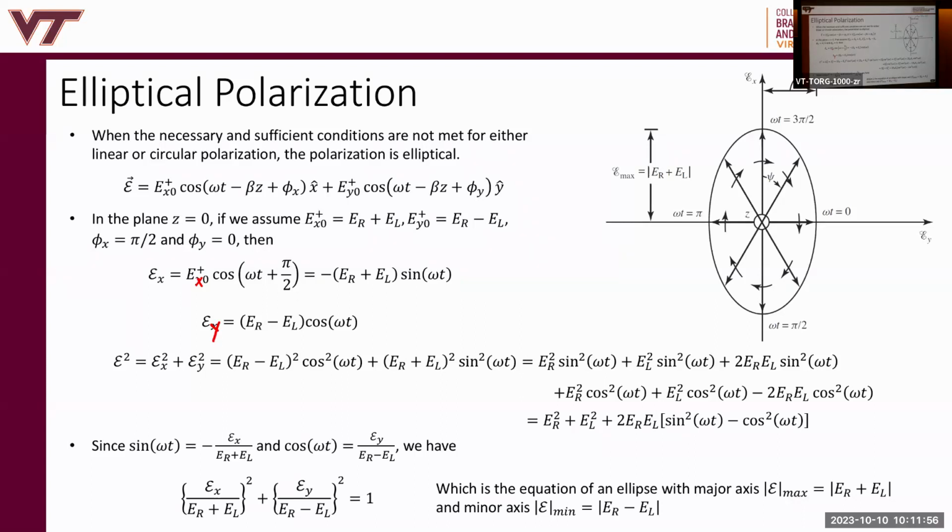The second bullet point says assuming that the phase differences for X and Y are off by 90 degrees, but that's not necessarily true, right? It doesn't have to be. We're studying this particular case first, where we've specified these to be 90 degrees and different amplitudes, just to highlight the difference between CP and EP, that the amplitudes matter. It becomes very hard to solve if you let those be arbitrary. The elliptical polarization can get kind of hairy, because then you would have cosine and sine, and these expressions become a little harder to combine.